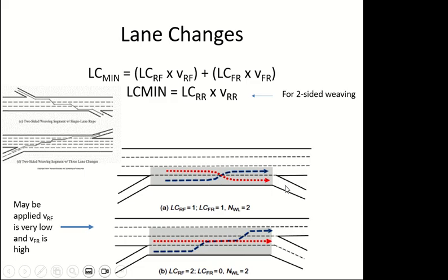He doesn't need a lane change here, but he decides let me go to the other lane and then come back to this lane. So this is an optional one for non-weaving people, people who are going from ramp to ramp or freeway to freeway. And on this side it will be the other way around. The required will be for ramp to ramp people, and the weaving will become ramp to ramp, and the non-weaving is basically freeway to ramp or ramp to freeway.